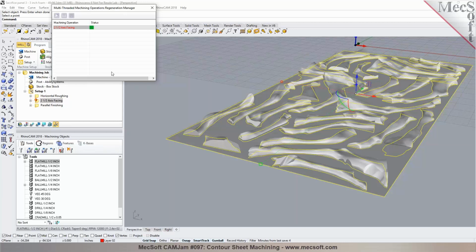Do you have any questions so far? Let me ask you a question. We have a situation where on some of our parts, the part is so steep that with the tools that we have, we can't get all the way down without the cutter hitting the part itself, or the tool holder hitting the part.